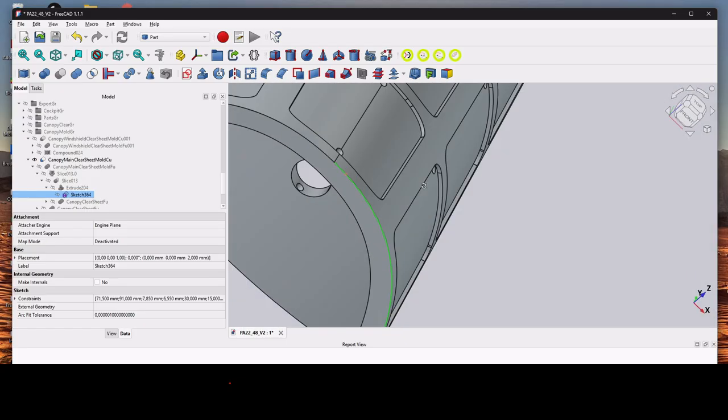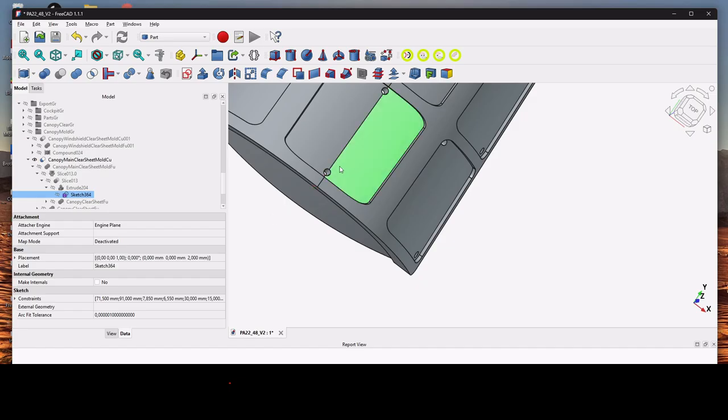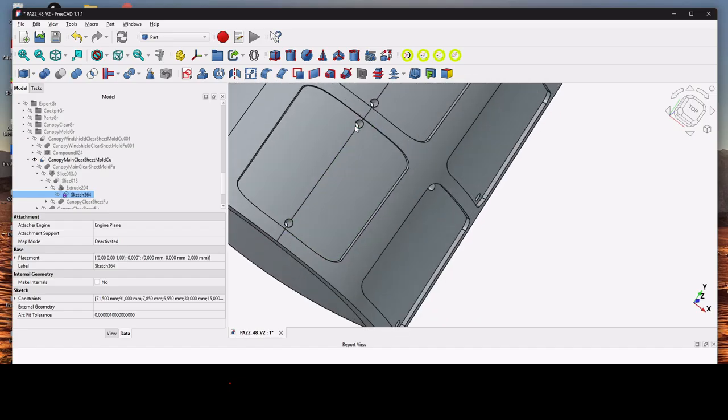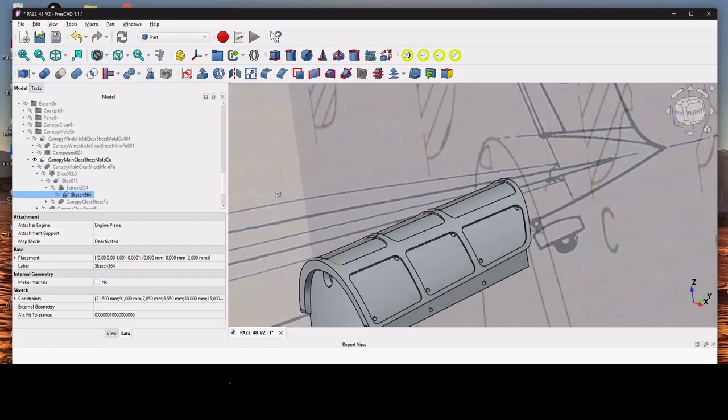So this is for the resin to get out, because those holes are too small for the resin to get out, but that will allow, when I'm vacuum forming, the air to go through that, and that in fact will allow the plastic sheet to really, I would say, follow those edges here.